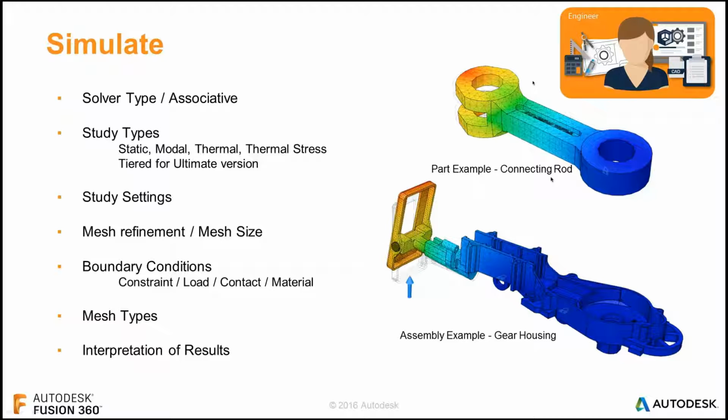It is important to note that for you Inventor users, the event simulation is different in Fusion 360 than it is in Inventor. In Inventor, it's more about if you drop a ball, it will bounce if it hits the steel plate, and what happens. Event simulation in Fusion 360 will allow you to drop something on something else and model how that object that got dropped on will break, how the material will release and tear and fragment. So pretty advanced stuff, in fact.